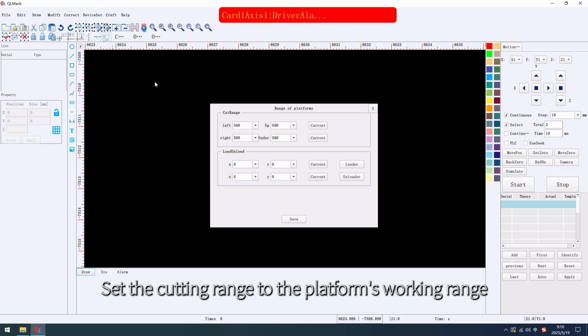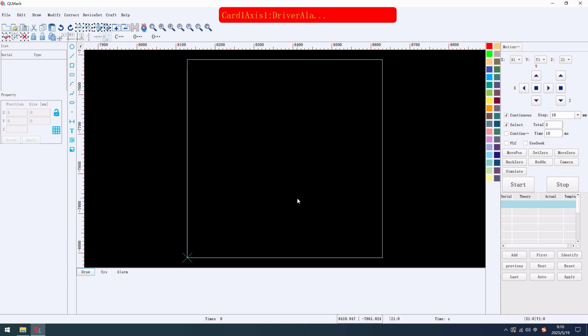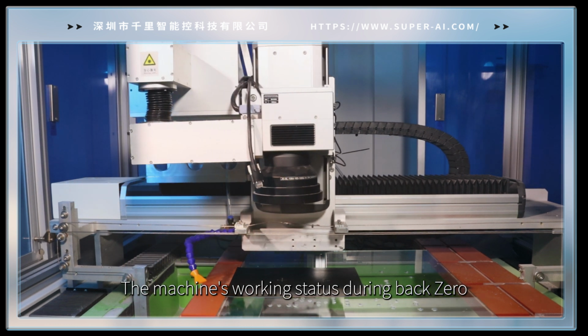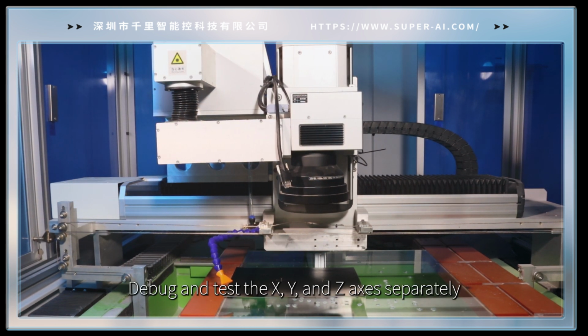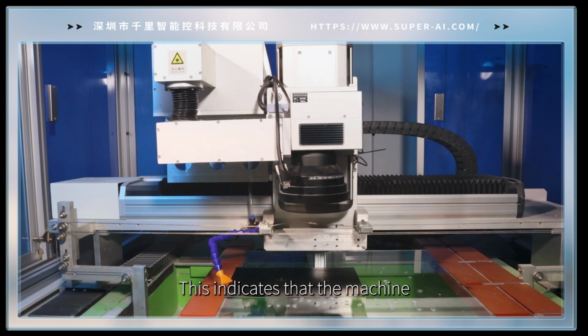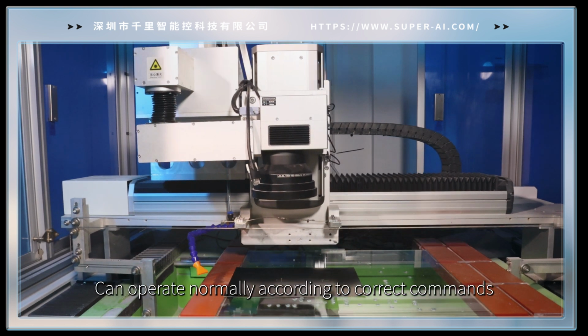Click Device Set. Set the cutting range to the platform's working range. Click Back 0. Begin the Back 0 operation. Test whether each axis operates normally. The machine's working status during Back 0 looks like this. Debug and test the X, Y, and Z axis separately. This indicates that the machine can operate normally according to correct commands.